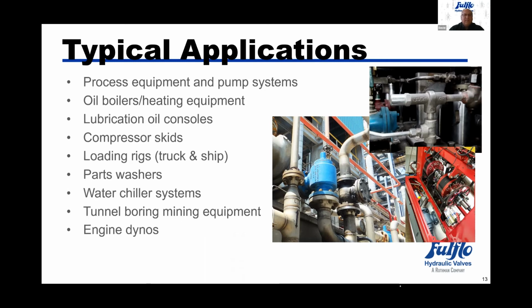Also loading rigs, similar to the example that I showed you before, that could be going to the loading rig, loading a truck or a ship or something to that effect. Once the truck or ship is full, the shutoff valve will be closed because the tanker is full. Therefore, you're going to get into a bypass situation. It's just a seal saver for a centrifugal pump where the pump doesn't have that strain on the mechanical seals.